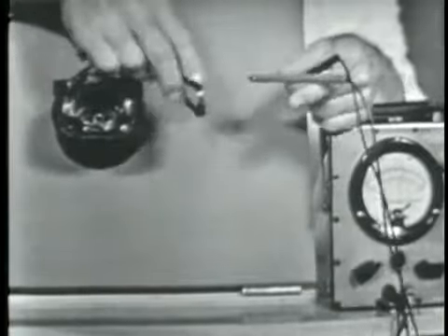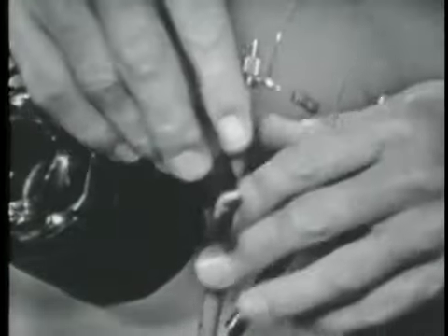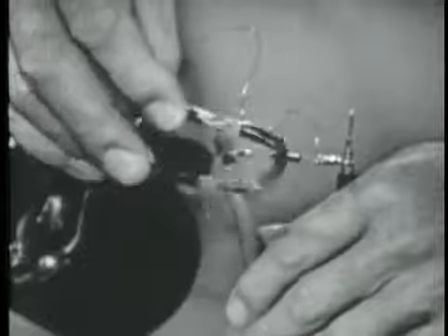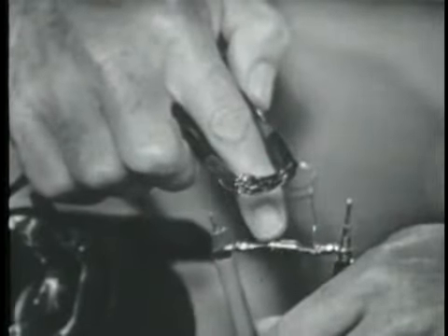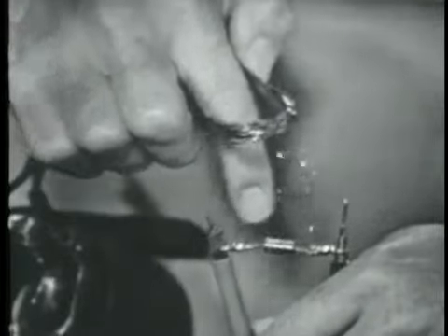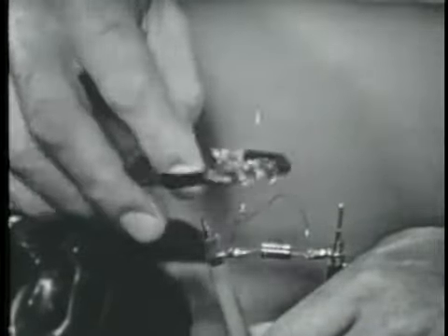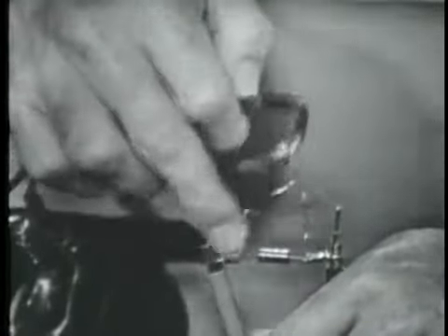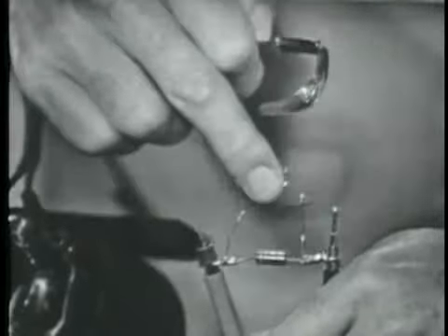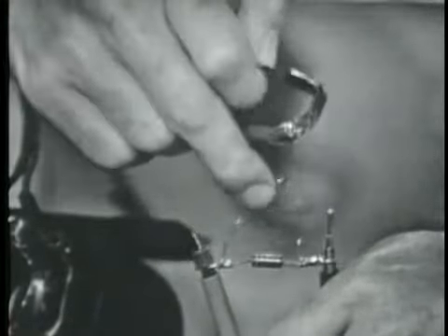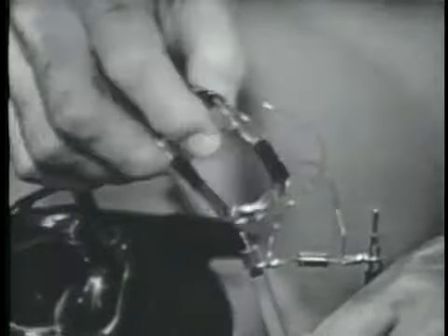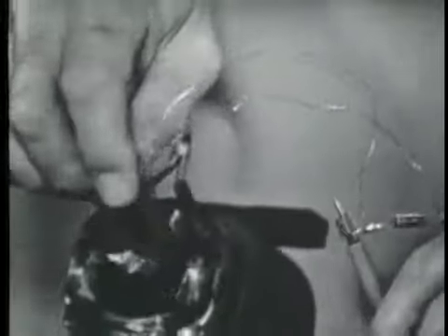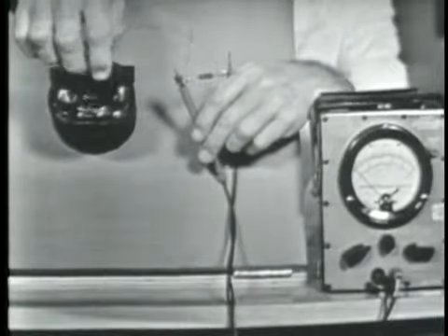Why don't you explain that, Bob? This is a coil of wire. The ends of the wire are connected to a resistor that is connected to the leads on our PSM6. And the object is, if we get current to flow in this loop, we'll have current flowing through this resistor, we'll get a voltage drop, and we'll read the voltage on the PSM6, okay? Okay.